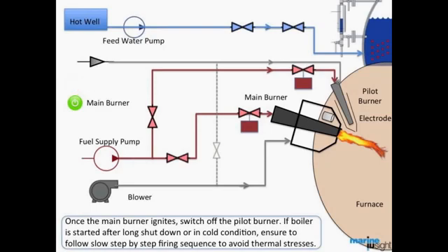If the boiler is started after long shutdown or in cold condition, always follow slow step-by-step firing sequence to avoid thermal stresses.